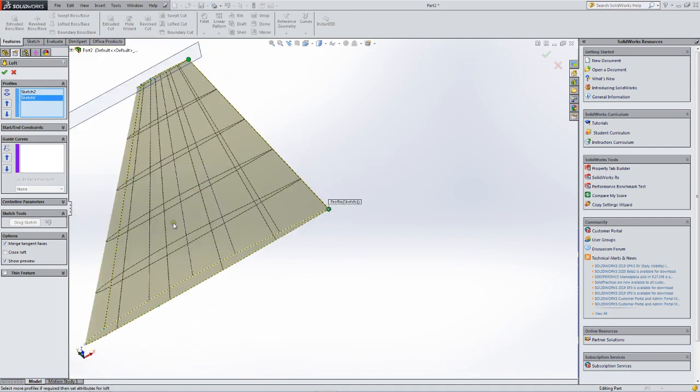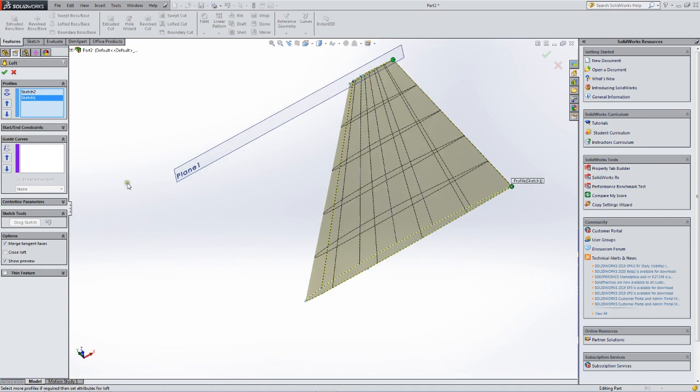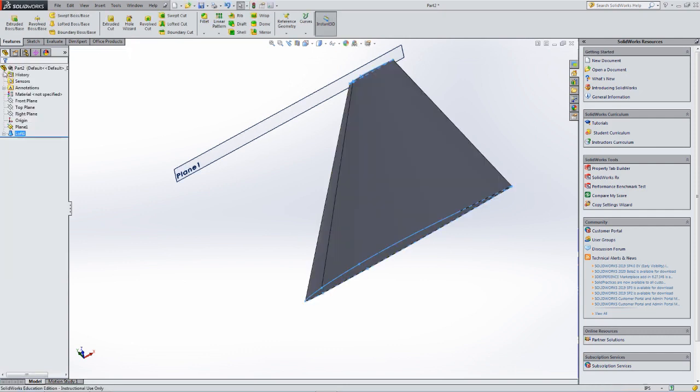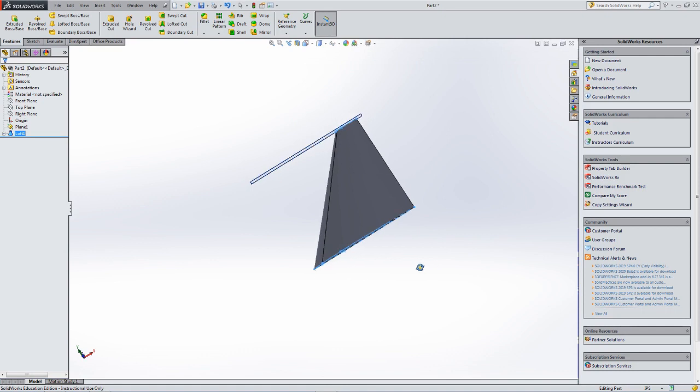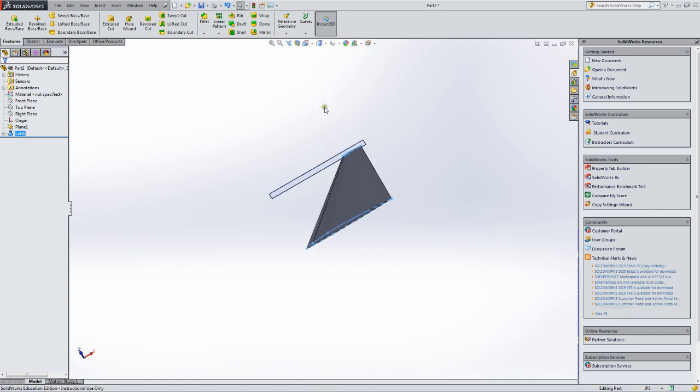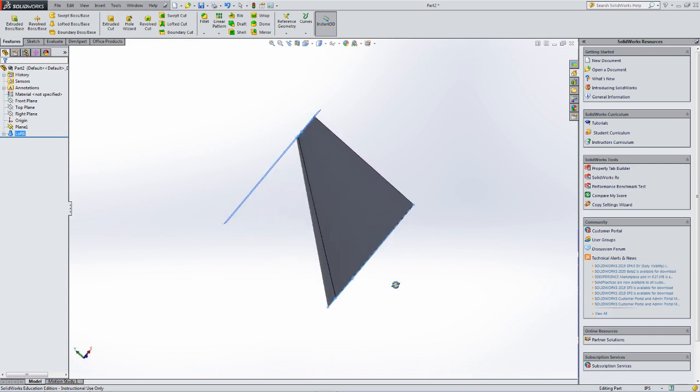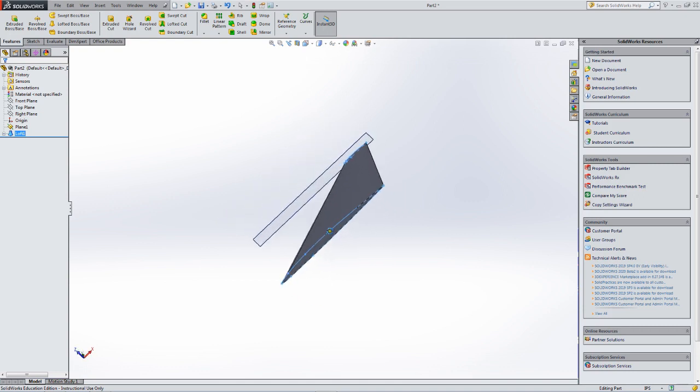It looks right. I zoom out, make sure, yeah, it looks kind of like an F-16 wing. And I'm going to hit the checkbox, and there it is. Now suppose we didn't want an F-16 wing. Suppose we wanted something more like a stealthy airplane. Well, we could move the wingtip about with that move function. We could change that sketch. We could change the root chord as well. Let's do that just to show how it could be done, and to get a stealthy wing that doesn't have a trailing edge at 90 degrees to the oncoming radar waves.